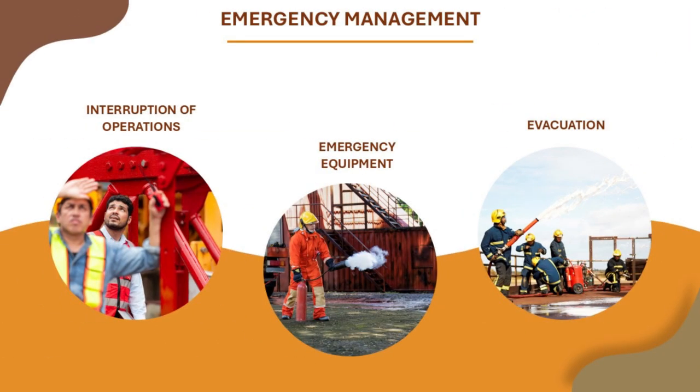Emergency management. Interruption of operations. Suspend operations immediately in the event of adverse weather conditions, such as strong winds or heavy rain, breakdowns or malfunctions, emergency situations such as falling loads or the presence of people in the maneuvering area.